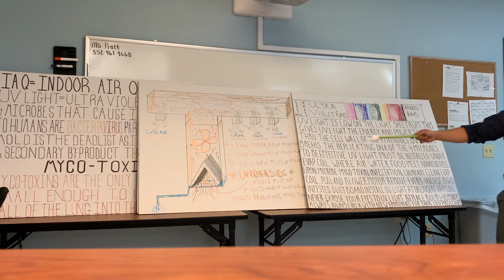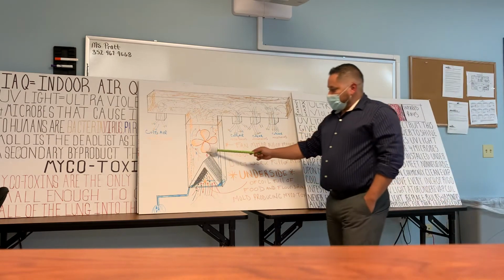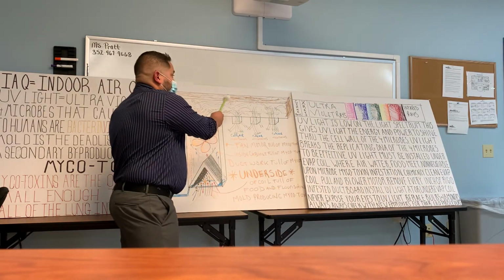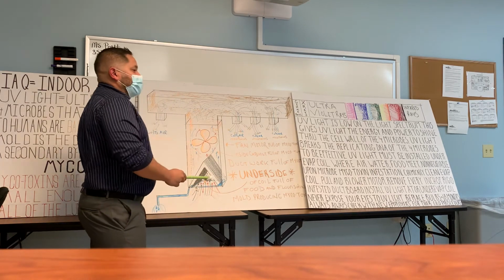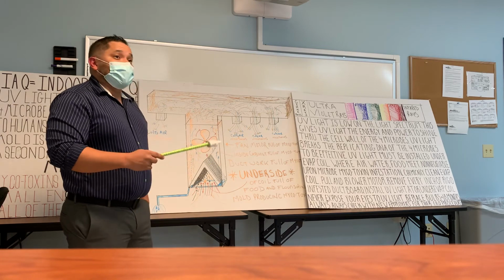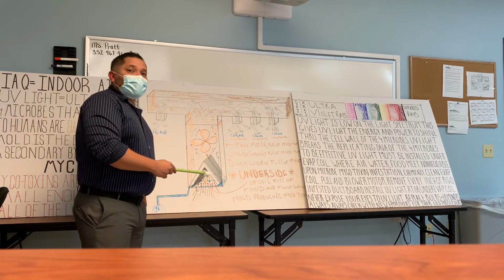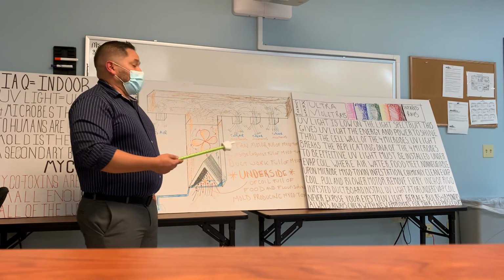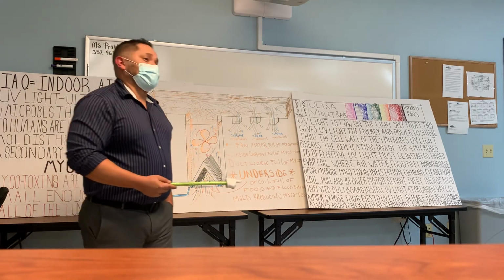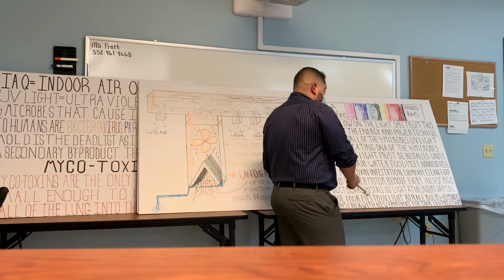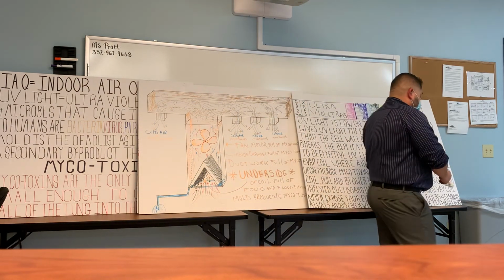you come up and you find a situation like this. And you tell the client, hey, you have mycotoxins, you have mold on your coil, but you don't realize that one of your other technicians or someone you work with was just there a year ago. And then that homeowner is going to be like, well, you guys were here a year ago, you didn't tell me. This is how lawsuits happen. So wherever you land, you always want to check with your new employer for their indoor air quality procedures.